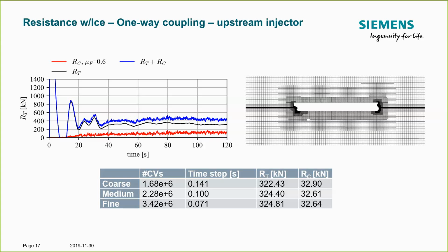What's more important for our problem, because we're very familiar with deep water resistance tests and their discretization errors, is looking at the contact forces. There are a few things that drive the change of contact forces in terms of discretization. The first thing is we changed the entire flow field, so every change in the flow field that is attributed to the discretization change will also affect the response of particles, even in a one-way coupling setting. In a two-way coupling setting, it might be even more severe.